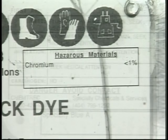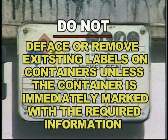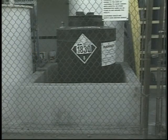Manufacturers of labels can provide a wide range of labels to meet your specific needs. Do not deface or remove existing labels on containers unless the container is immediately marked with the required information. Basically, every chemical must be identified and labeled, regardless of the size of the chemical container.